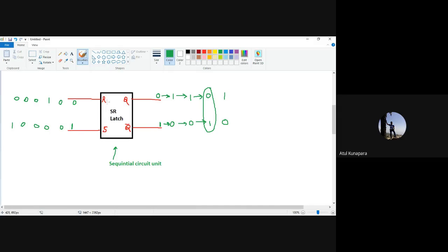So this SR latch or flip-flop, you can consider it like a memory, or you can say a 1-bit memory. So it will be working like a memory, right? How is it working like a memory? You can see that unless you give the input on this side, your output is going to be kept constant at whatever logic it was set by the input condition, right?